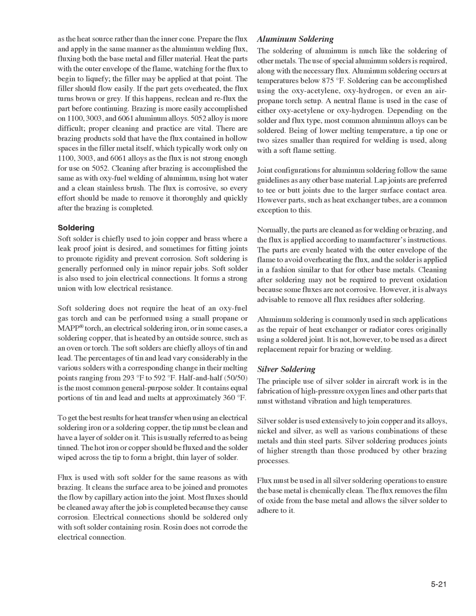The filler should flow easily. If the part gets overheated, the flux turns brown or gray. If this happens, re-clean and reflux the part before continuing. Brazing is more easily accomplished on 1100, 3003, and 6061 aluminum alloys. 5052 alloy is more difficult. Proper cleaning and practice are vital.